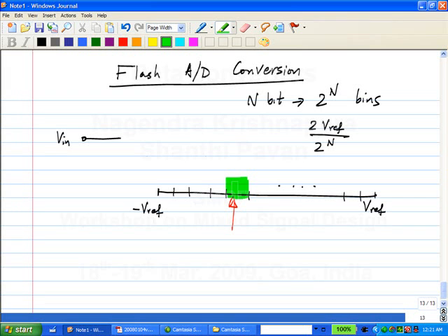And as Nagendra pointed out, this process involves some error, right? Okay? And so, in other words, the error is happening because for every analog input in this range, the output is the same output, right? So the output of the A to D converter is basically, it's going to say the input was in the 17th bin, no matter what exactly the input was in this range, right? So clearly, this is quantization and this is an error prone process, and we have gone and calculated how much error there is and all this wonderful stuff.